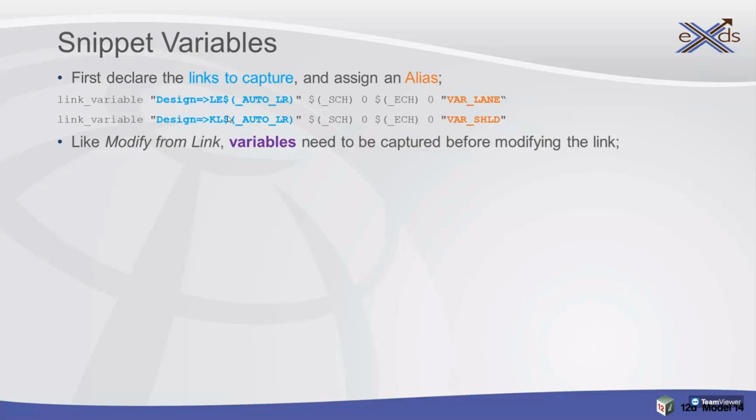If you were to modify it halfway down the road from 3.5 to 5 meters, and you capture the value after you've modified it, then you will actually have different values. It'll be 3.5 meters where it's 3.5 meters, but then when it widens out to 5 meters, the value of your variable will be 5 meters. So it's all very dependent on the order that you capture things. And the good part about it is that you can capture a value and store it to use later, so that when you modify strings, you can reuse the original value to pull everything back in line.